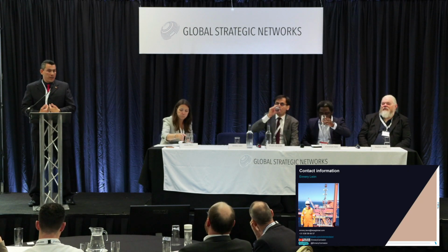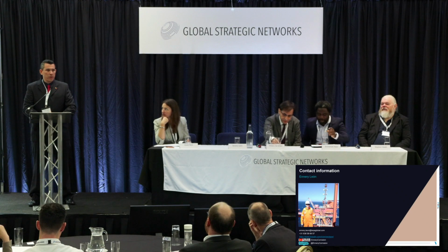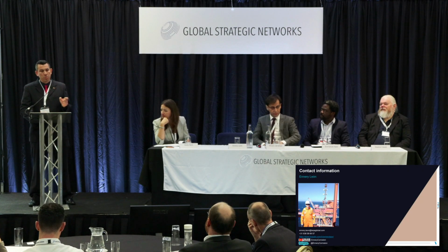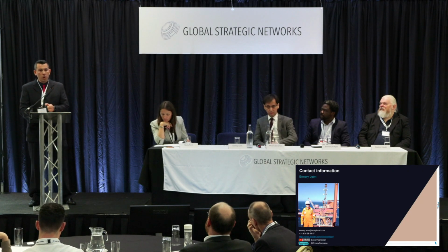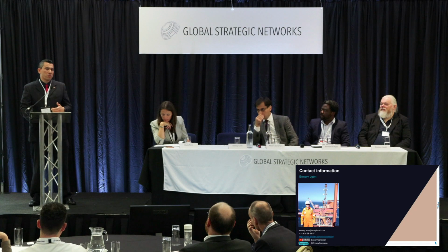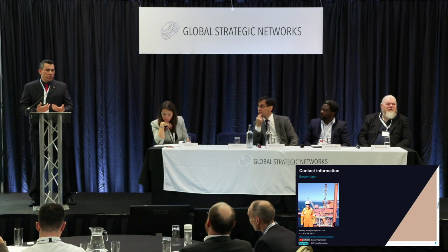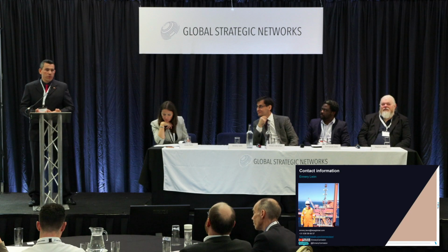In my case, we don't need quick responses in the matter of hours. We can have more robust ER probes that can last longer and give me some information because my process is quite stable. So if I understand your question correctly, you need to go case by case and ask yourself, how quickly do I need feedback? Does that answer your question?